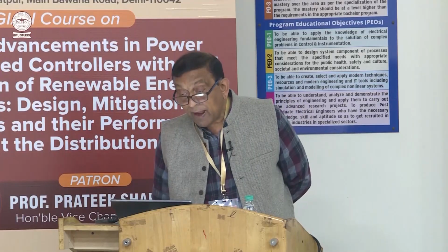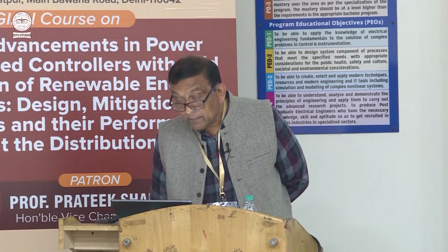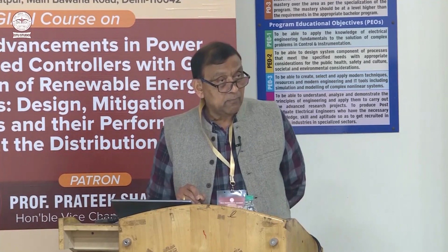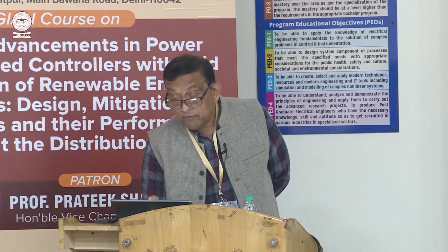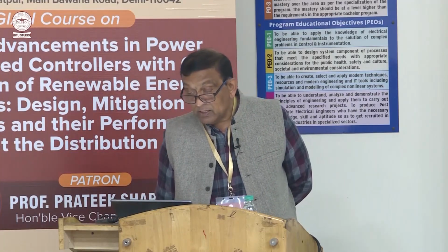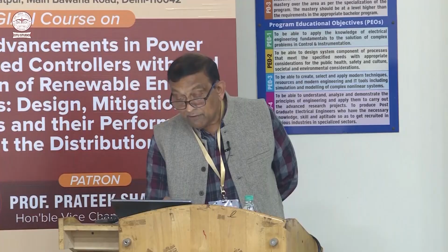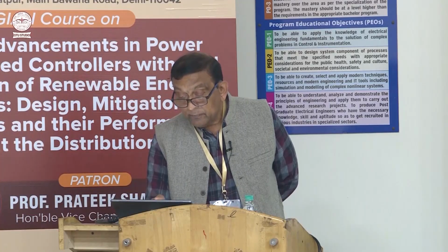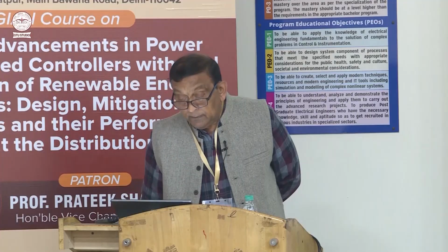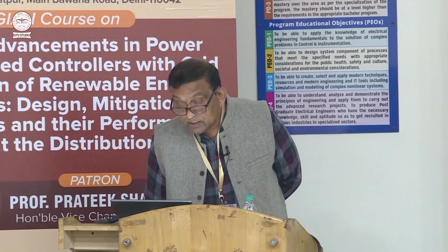While in DY11, it was 7th harmonic shifted by minus 30 degree and 5th harmonic shifted by plus 30 degree. So you have to see the difference. Okay, 7th harmonic plus 30 degree, 5th harmonic minus 30 degree. So this is what we have seen.